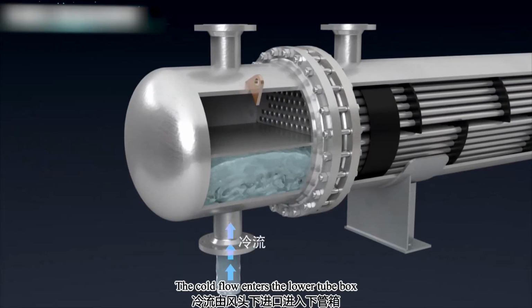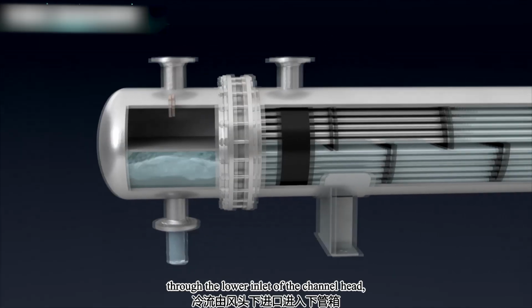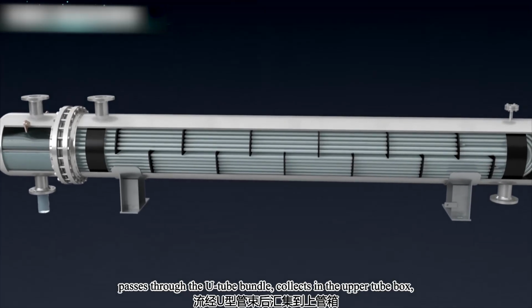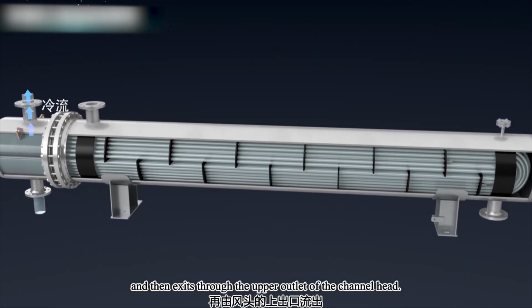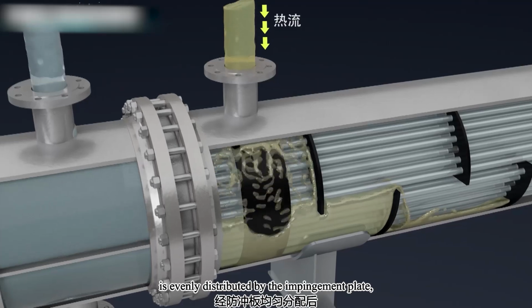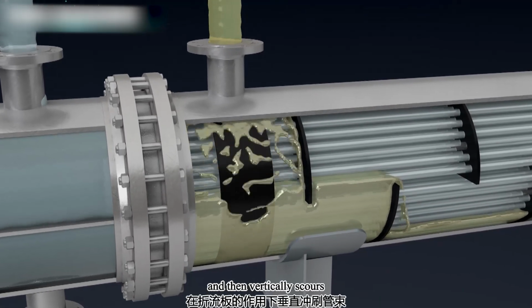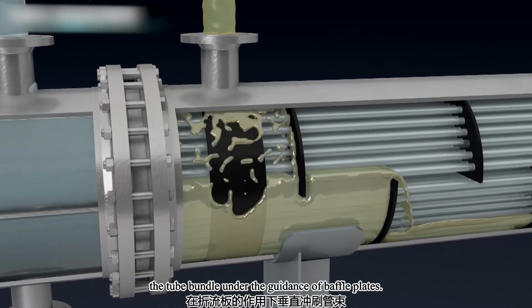The cold flow enters the lower tube box through the lower inlet of the channel head, passes through the U-tube bundle, collects in the upper tube box, and then exits through the upper outlet of the channel head. The hot flow enters the shell side through the upper inlet of the shell, is evenly distributed by the impingement plate, and then vertically scours the tube bundle under the guidance of baffle plates.